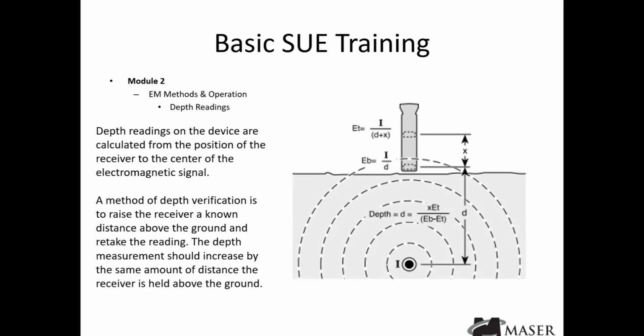The way that the system calculates depth is that there are 2 antennas in the system: antenna top, antenna bottom. As the signal that is propagated is received by both antennas, there's a calculation made about the time that it takes between when the antenna at the bottom received the signal and when the antenna at the top received the signal. And that time differential calculates to a depth.